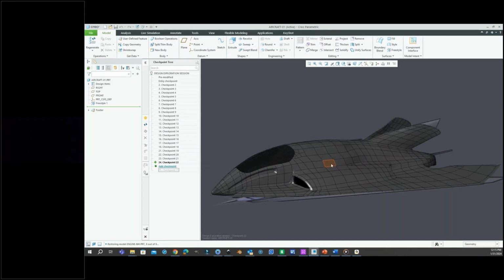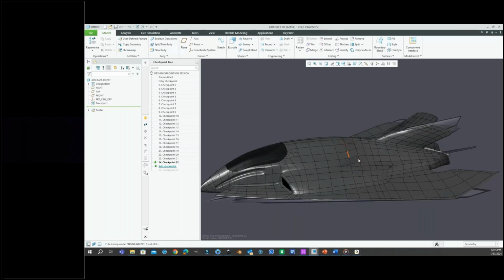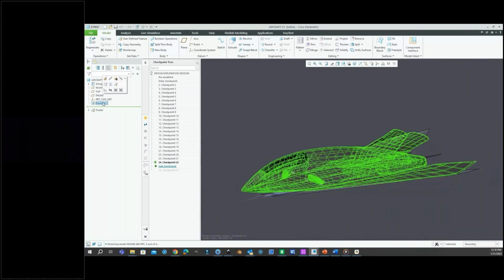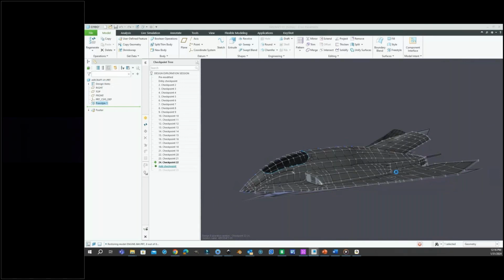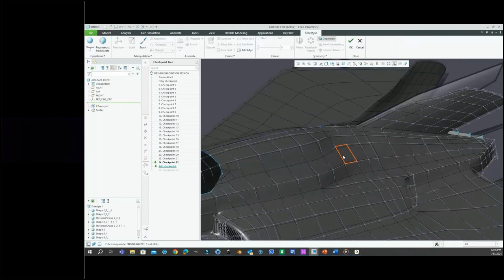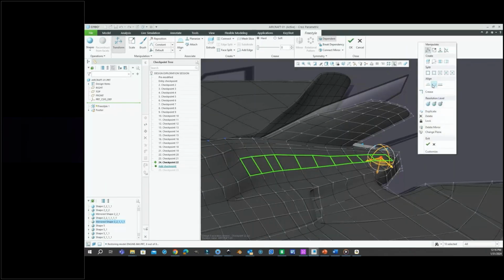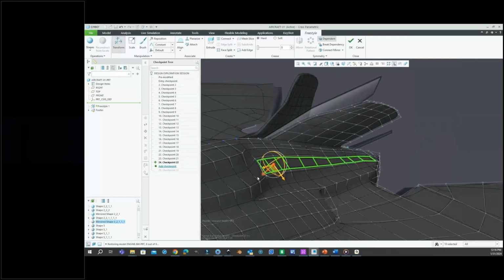So for example, if I'm like, hey, I like this version, I want to explore this more. Maybe I want a little bit of an indentation here at the rear of the jet. I can go into Freestyle. Maybe I'll select some of these faces here, and I'll do a split, and I'll add that cut feature in the mesh or the indentation. Click OK.